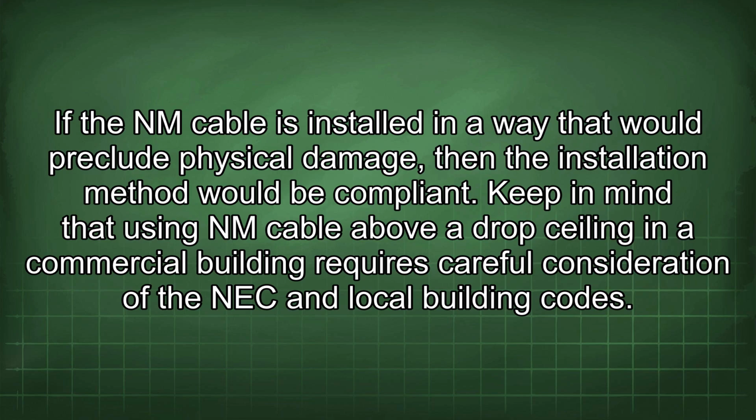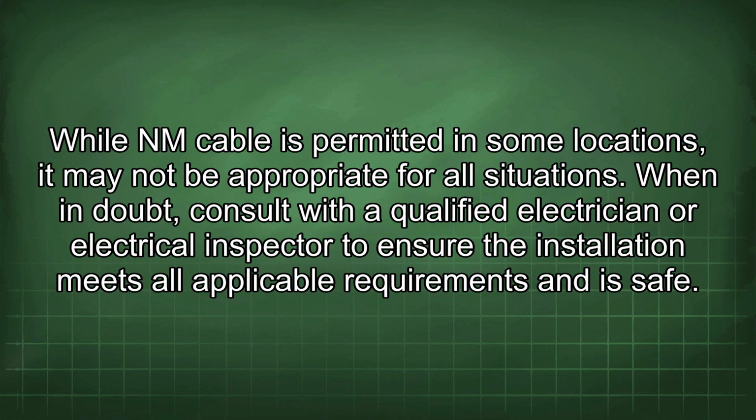Keep in mind that using NM cable above a drop ceiling in a commercial building requires careful consideration of the NEC and local building codes. While NM cable is permitted in some locations, it may not be appropriate for all situations. When in doubt, consult with a qualified electrician or electrical inspector to ensure the installation meets all applicable requirements and is safe.